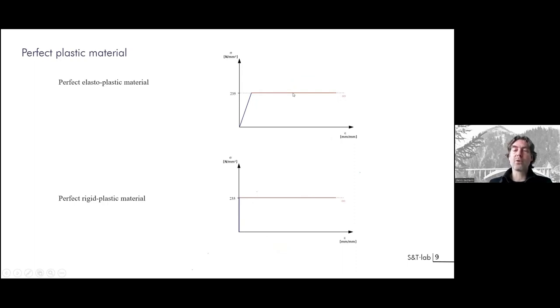And that's very important. It means that with such a material, you just have to wait for the system to reorganize itself to reach an equilibrium, a state in equilibrium that guarantees that it can support loadings. And since this zone is supposed to be infinite, you can also, neglecting the third zone of the elastic zone, just have a rigid plastic solution. What's the connection with the true material?